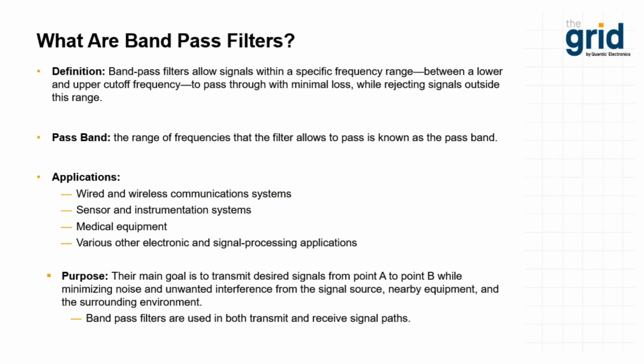And without a filter there, you could spray information over a part of the frequency spectrum that you don't want to contaminate. Also, in the reverse direction, if you're using them in a receive situation, a lot of times there can be interfering carriers that you pick up on your antenna, and they can overwhelm your low noise amplifier. You don't want that to happen either, and bandpass filters are perfect for preventing that from happening.